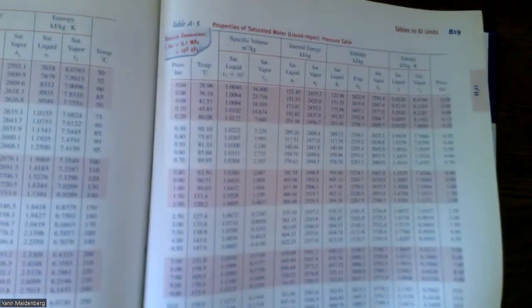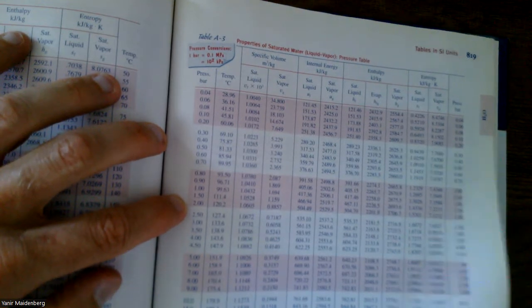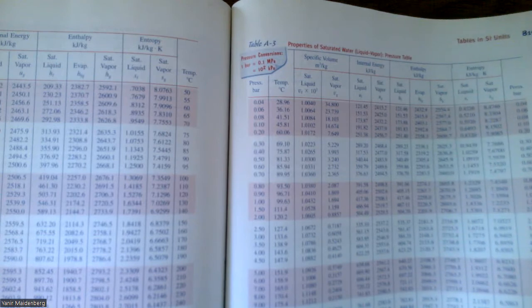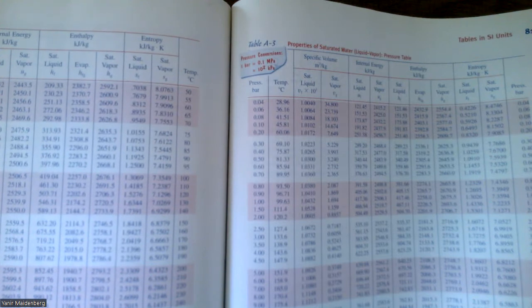And just to convince yourself, we can look at the saturated water in terms of pressure. It's the same information again, just organized in terms of convenient pressures. And we know that we have 60 bars, and when we look at 60 bars, the corresponding temperature here is 275.6. So we know for a fact it is not saturated. So our options are that this is going to be a liquid, which really wouldn't work well for this turbine, since we specified this as steam. So it's more likely going to be superheated steam.